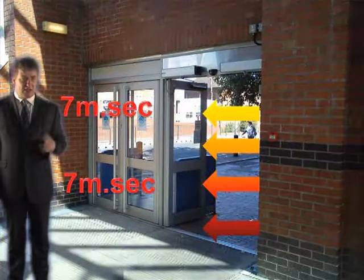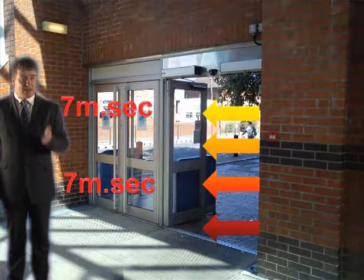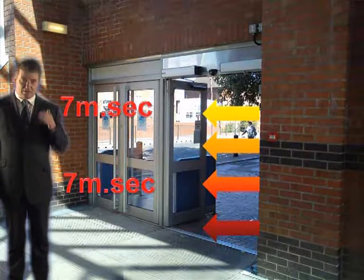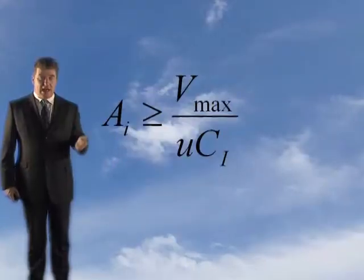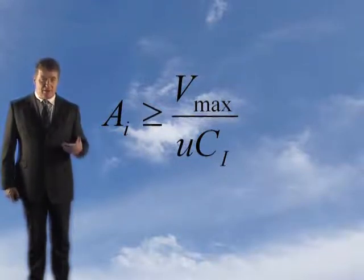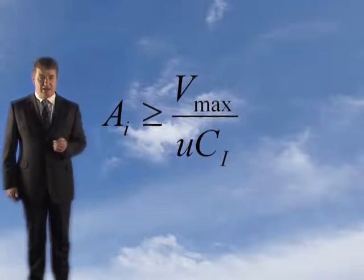Now, the maximum velocity that is allowable for the incoming replacement air is 7 metres a second for an office building. Don't forget, if it's the general public coming in, you've got to reduce it down to 5 metres a second. Now, we need to check the air inlet velocity using this formula here. AI must be greater than or equal to your Vmax divided by your UV, your velocity, times your C, the coefficient of your inlet. If all the fans are in use, there are 4 fans extracting, so you've got to assume all 4 kick in. So you've got 11 metres cubed a second from each. It gives us a total extraction rate, which is your Vmax, of 44 metres cubed a second.